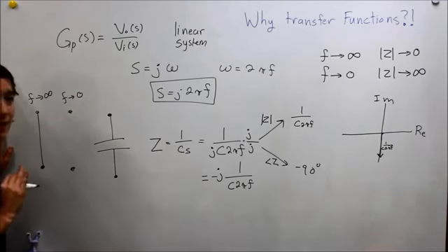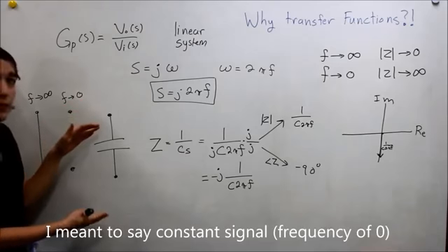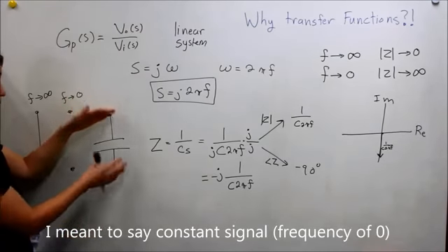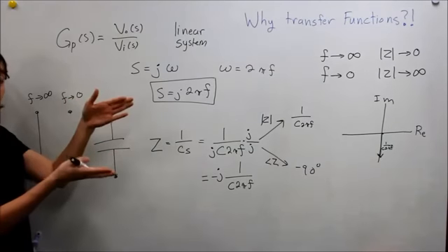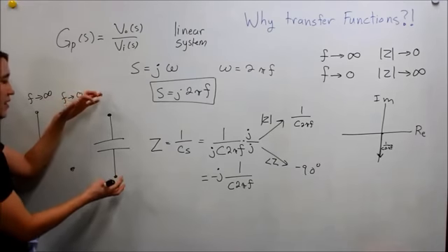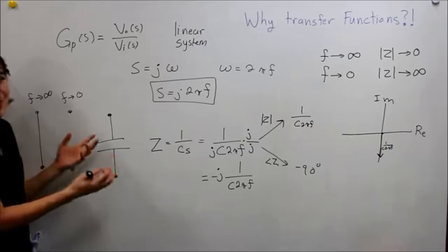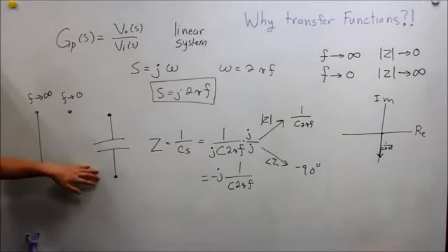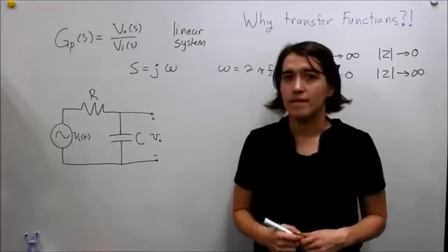And the way I like to think about this is if you have a capacitor and you put just a stable frequency over it, it's not going to do anything. It essentially acts as an open and just holds the charge, holds the voltage. If we put a lot of high frequency into it, it'll become like a short. It has a very low impedance. So we can actually use this in a system now, which we're going to do in a second.